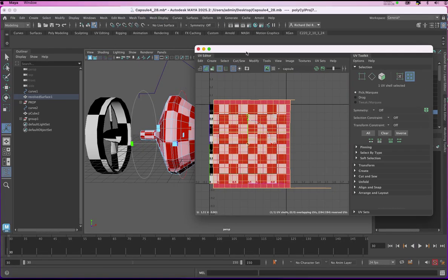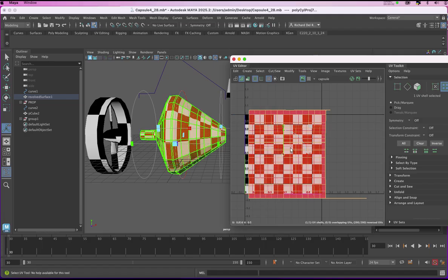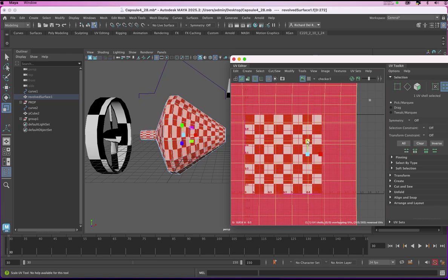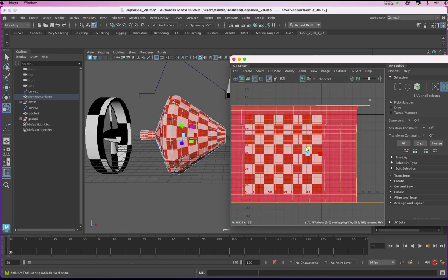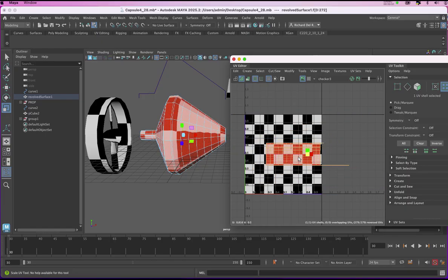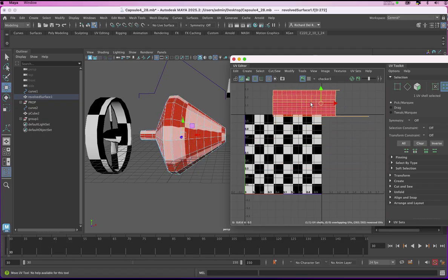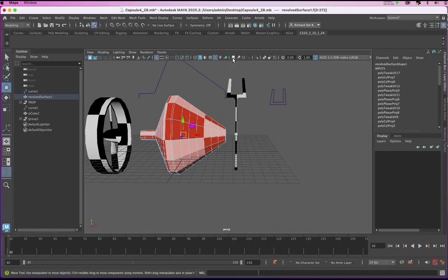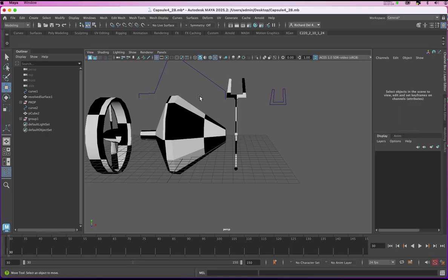And in the editor, I'll right click and choose shell, selecting the shell. I'm going to scale the whole thing up because I want those boxes to be more square. Now I'll drag on the y-axis to square them off a little bit more, as you can see right in here. And now I'll scale it from the center in to fit inside the UV quadrant. And I'm going to put that just outside the box for a moment. I'll return to my viewport, right click, go to object mode, and deselect.